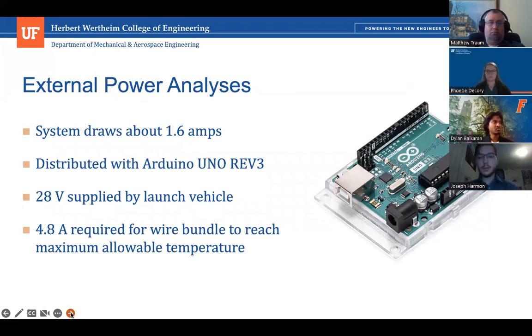So for the entire power, we receive the 28 volts through the DB9 connection port, which then transfers to power an Arduino Uno and multiple digital potentiometers. The digital potentiometers then distribute the power to each subsystem in accordance to the signals produced by the Arduino Uno. The Uno interprets and acts on the signal received by the patch antenna, which I'll describe shortly.